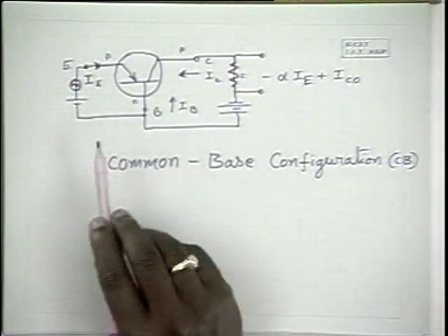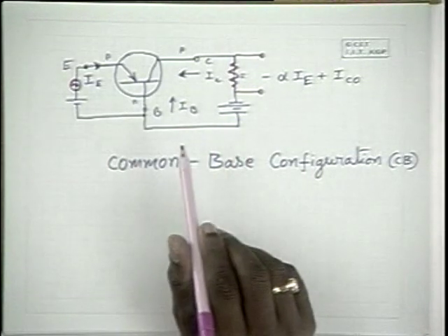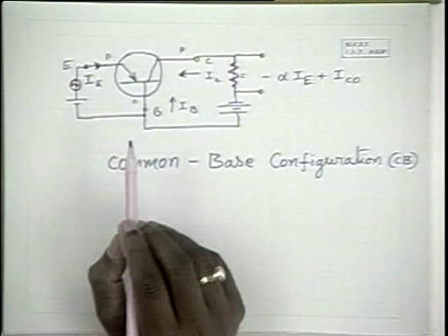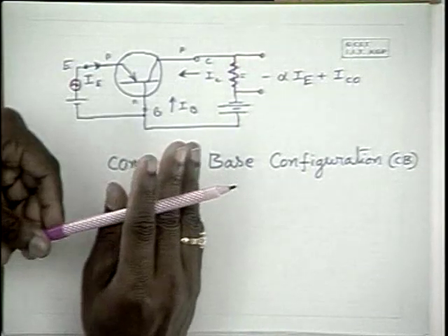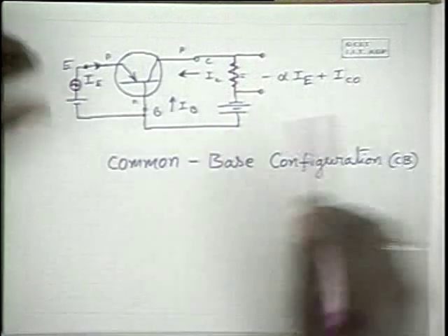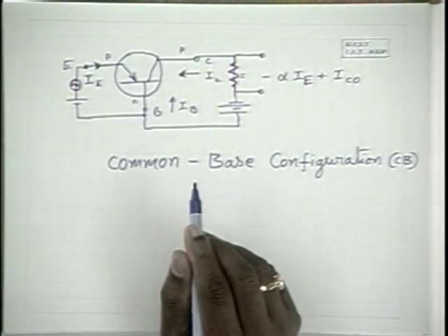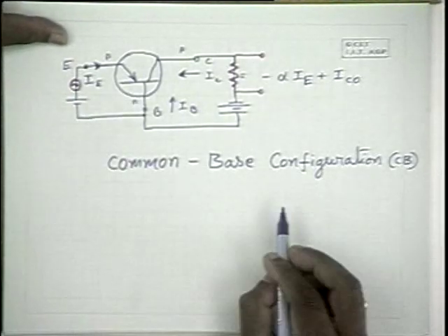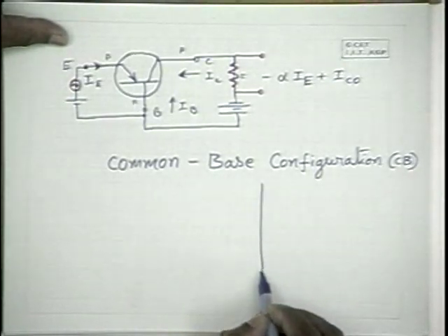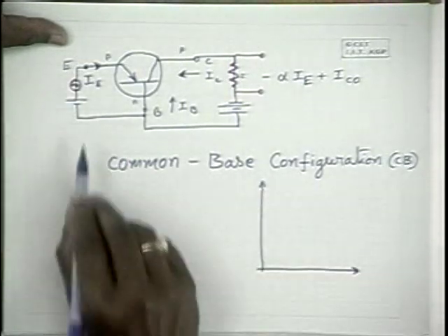When you form an amplifier with this kind of input and output arrangement, you get some kind of amplifier with certain characteristics, like a high voltage gain amplification and low input resistance. Similar to this, you have different kinds of characteristics of the amplifier that come into the picture. Hence in this case, the emitter-to-base junction is the input junction and the collector-to-base junction is the output junction. Now let us look at the characteristics of the amplifier. If you look at the input characteristics here, between the emitter and base, it is a PN junction.